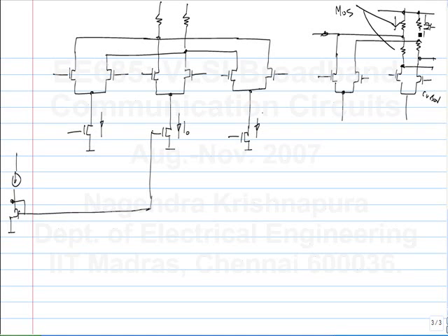Thought we discussed this once already, right? Yeah, we can vary the currents. How do we do that? Current steering. So there are various ways of doing it. One possibility is to have multiple transistors here. You split a single transistor into multiple transistors. If you have all of them on, you get the maximum current flowing through this, and you can selectively turn some of them on and off. Okay, and to turn them on and off, you can do this.